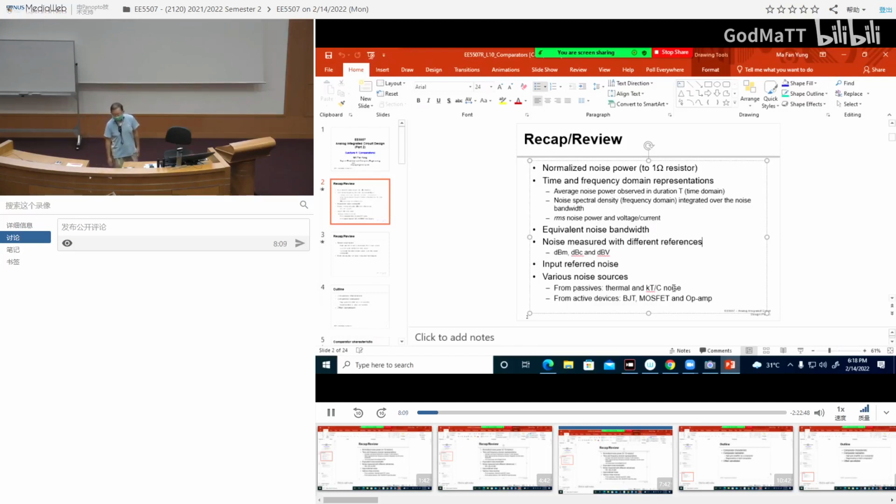Sometimes, if your professor or your friend asks you, hey, I want to use a very big resistor to reduce the current, so I will use a very big resistor. Yes, the current will go down. But what is the price you pay? Noise. The bigger the resistor you put there, the bigger the 4kT/R noise. So there is no free lunch.